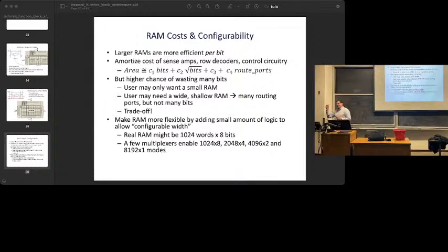We could look at one address bit and basically multiplex between pairs of 4-bit outputs and just send that to the routing. Or we could look at 2 address bits and multiplex between sets of 2 outputs. Or we could look at 3 address bits, and we could actually multiplex all of those, that 8-bit word, to choose which bit within it you actually wanted and send that out to the routing fabric.